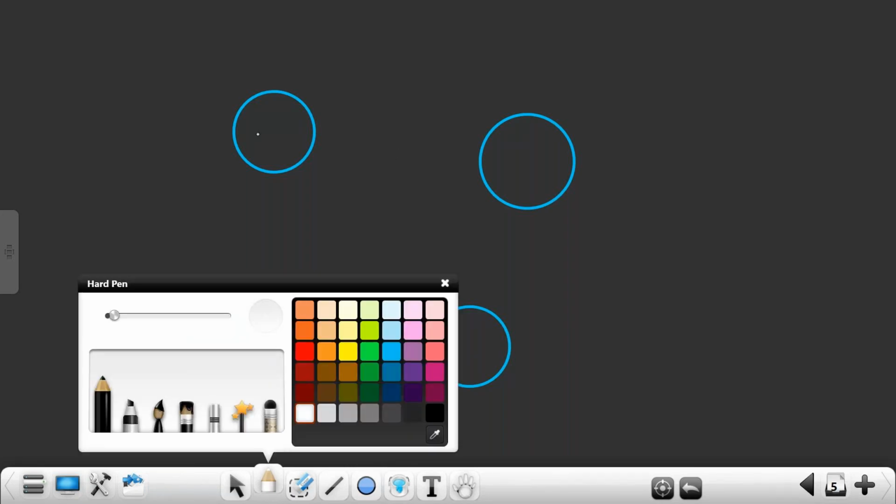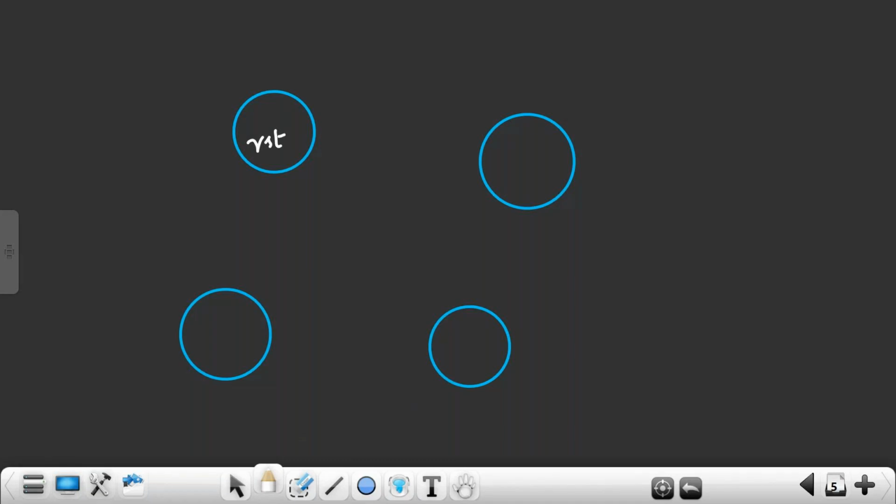So when it is in reset state, reset state means welcome to Canara Bank. Some photos will be shown on the screen, right? That is reset state. If card is not inserted, the input is 0. Card is not inserted means for the IC the input is always 0. If card is inserted, the sensor will give me logic 1 as input. Then automatically I go to the next state. If card is not inserted, be always in reset state. If card is inserted, go to the next state. This state is called the pin entering state.